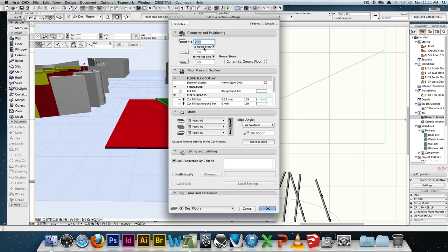Slabs and walls are kind of the same. In a slab, though, we always define the height of the slab as being the top surface of it. So that's the height of our slab, always the top surface. Whereas a wall, we define it as being its base. So we say of a wall, the base of it is 100 and it is 5 metres high. Slabs, we say the top surface is at 0 and it's 200 deep. So, yeah, two different ways of thinking of the same thing. However, that T and B are the same, the top height and the base height.